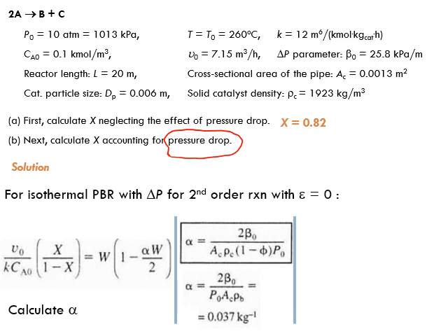This is the pressure drop parameter. So we have two pressure drop parameters in the Ergun equation and the modified form of the Ergun equation. We have the alpha and we have the beta naught. Beta naught is basically a property of the bed and the flow at the entrance, and alpha depends on other parameters like beta naught, P naught, cross-section area, and the bulk density. Okay, so we calculated alpha. Actually, the alpha is some value per kg of packing.